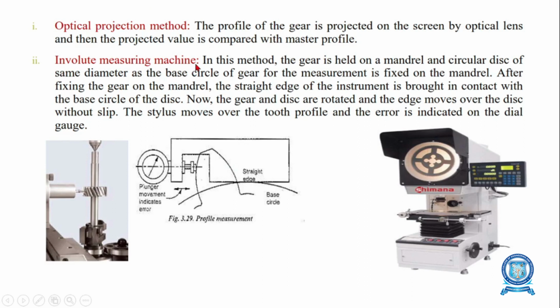In the optical projection method, the magnified profile of the gear is projected on the screen by an optical lens. Then the projected profile is compared with the master profile.